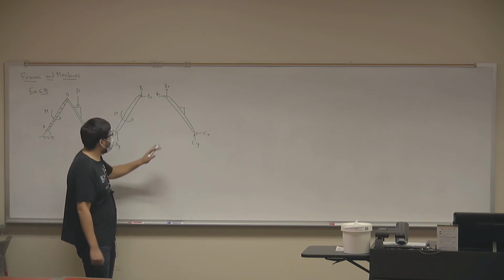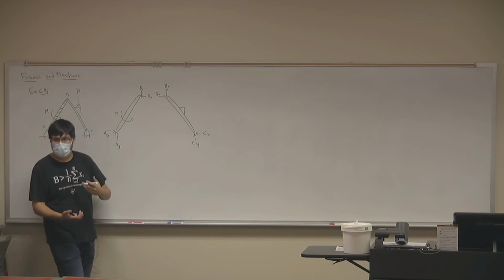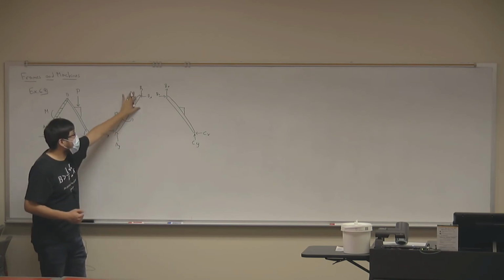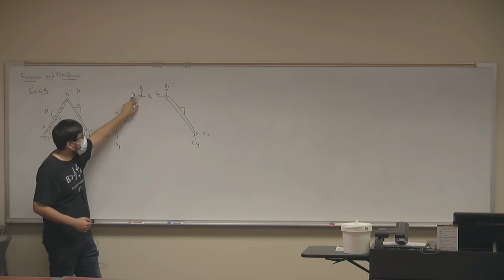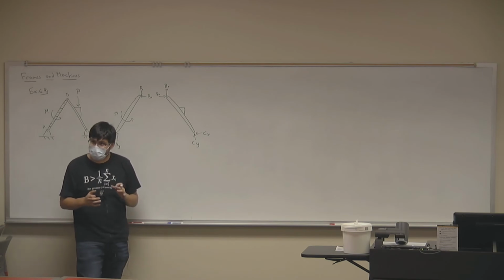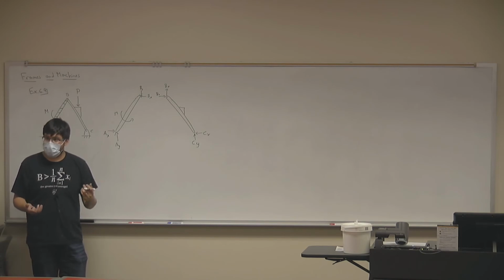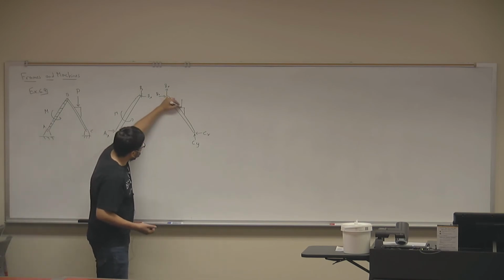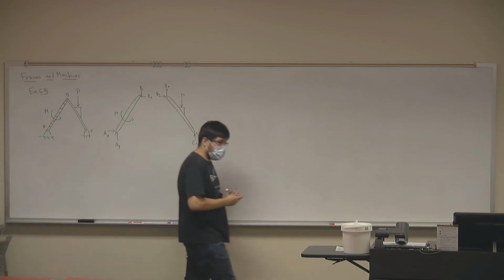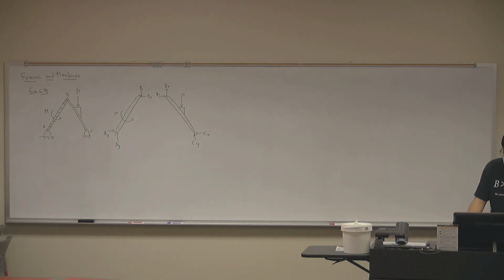So where are we getting this from? Remember, for every action, there's an equal but opposite reaction. So if we have a force Bx and By in the negative direction for both here, it's going to have to be in the positive direction for both there. Now this is going to start getting a little bit confusing, because now we're considering more than just tensile or compressive forces. And of course, let's not forget our force P. I feel it's better if we look at it by working through an example.